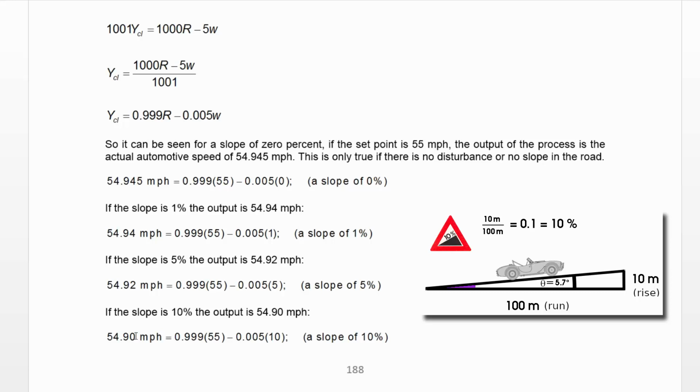And again, it just takes the error, from what it is and what you're looking for, and it multiplies that times the gain, and then it adds that to the output if it hasn't reached the set point. After, say, you got 1 repeat per minute, that means it'll repeat that error. It'll add that to the output.